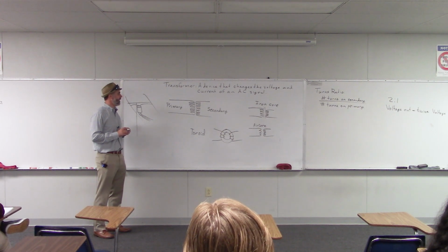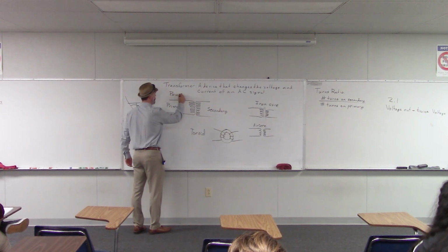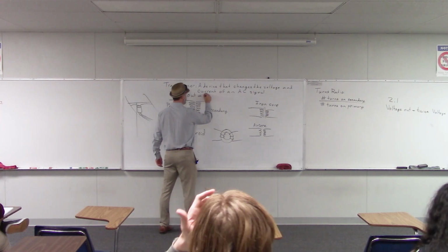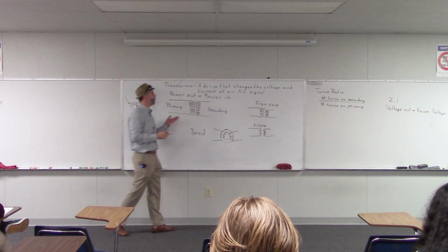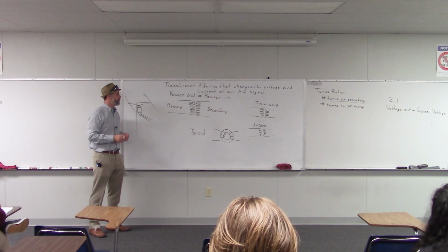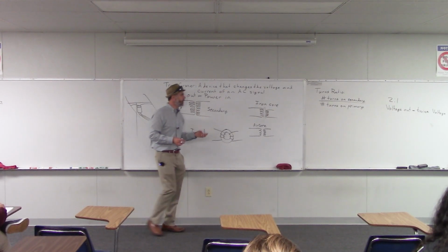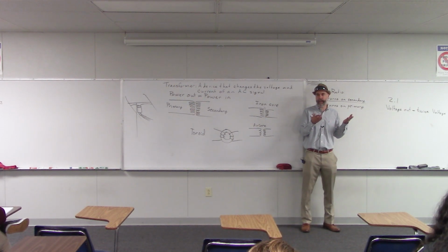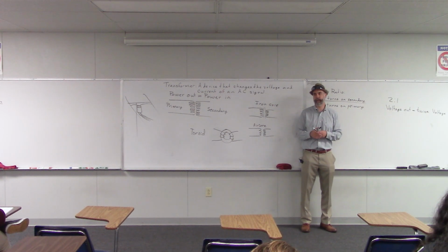The thing is that the power out of a transformer equals the power in, okay? So you can't make more power coming out than you have coming in. And remember, power is voltage times current. So what that means is that if you boost the voltage by a factor of 2, the current gets cut down by a factor of 2.